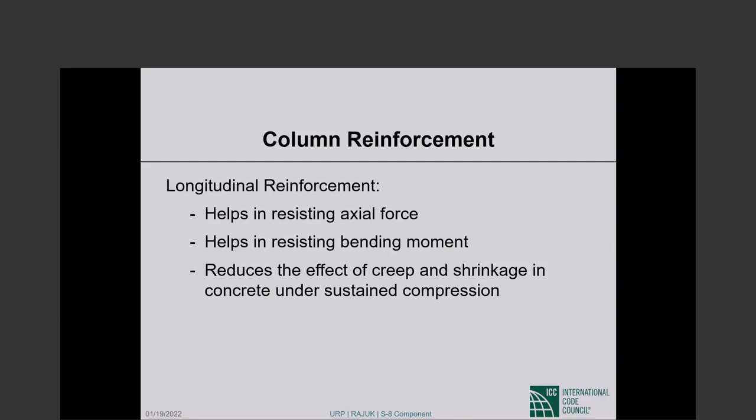Okay, so shrinkage, you know, is the evaporation of water out of the concrete, a load-independent phenomenon. Creep is a load-dependent phenomenon. If you keep a compression on a member, the immediate deflection due to the compression load will increase with time, and the time-dependent increase is called creep. Now, the shortening,